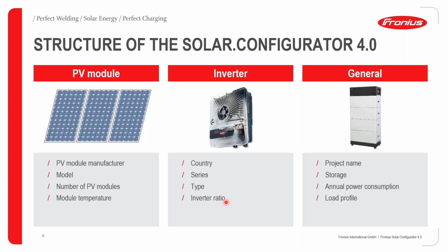Just remember, for all our 2-tracker inverters from Fronius, you can oversize the DC to 150%. So I can pretty much attach 15 kilowatts worth of modules onto a 10 kilowatt Fronius inverter. Just remember, at the end of the day, we will still get 10 kilowatts output. We will just ensure that we get that 10 kilowatts of output for a much longer duration of time.